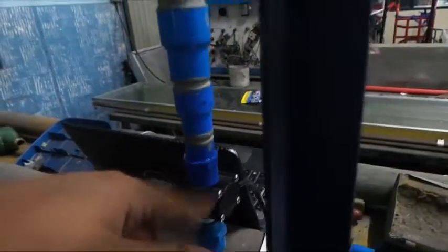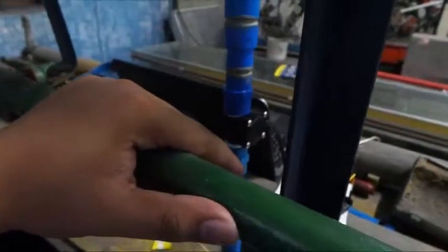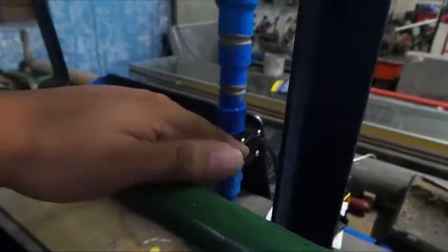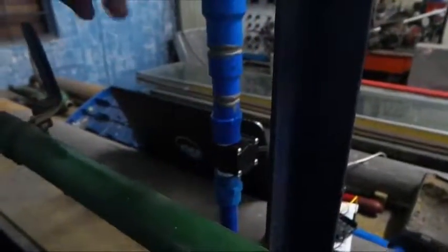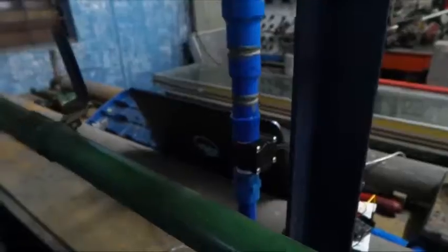And the flow meter then calculates the number of pulses of water that goes through. You may ask, what are pulses? Pulses are the number of cycles in the rotor of the flow sensor based on the amount of the water that goes through it.